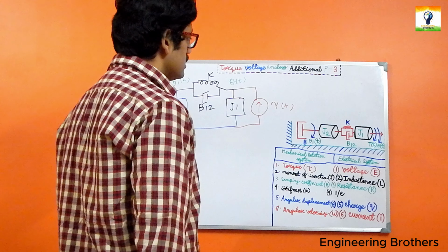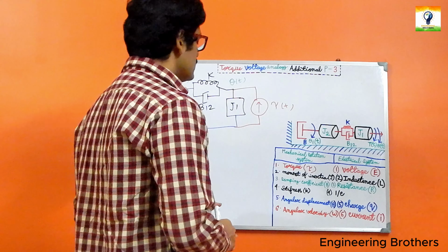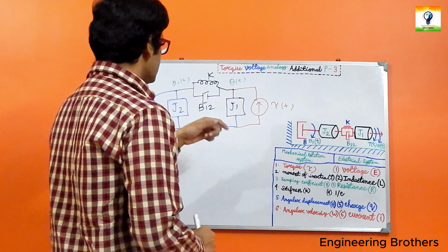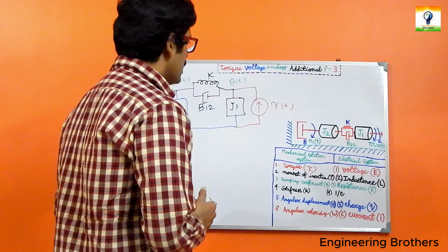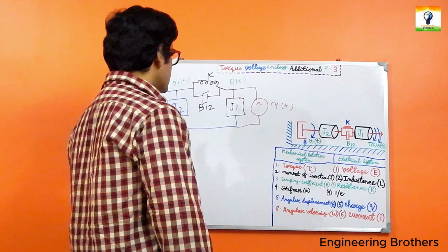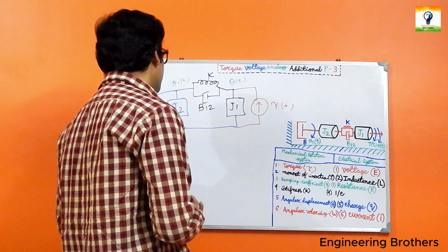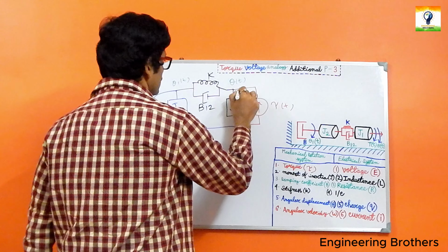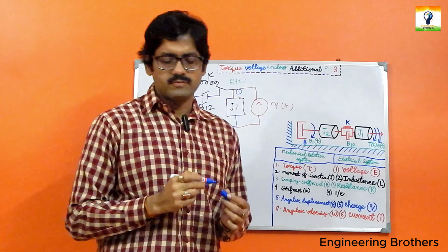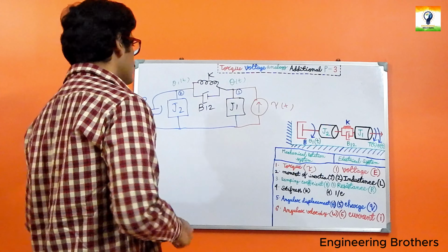Quite naturally, for the rest of our consideration with theta 1t, J2 has been connected there and B has been connected here. Now we have to include the torque at the right hand side. So this is the much needed conventional nodal diagram, and this is our node 1 and this is our node 2. Now in our next step, if we apply the D'Alembert principle on node 1, what is going to be the equation?